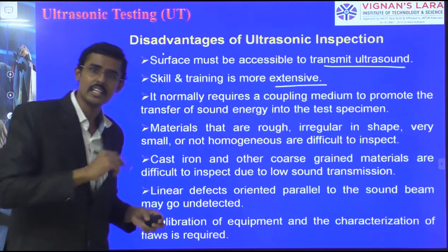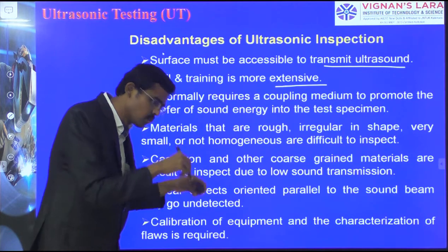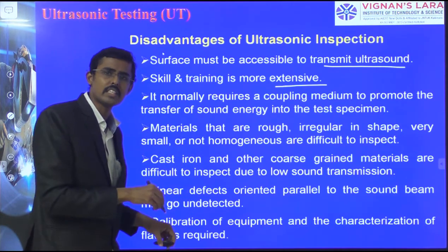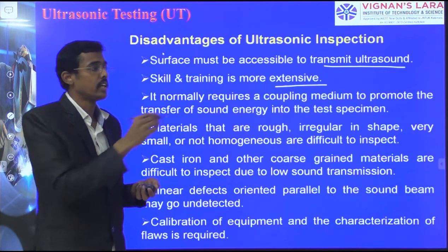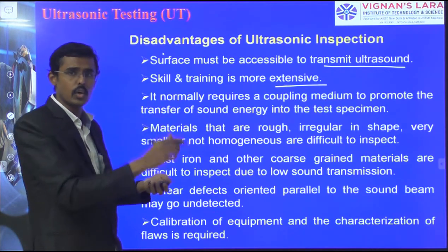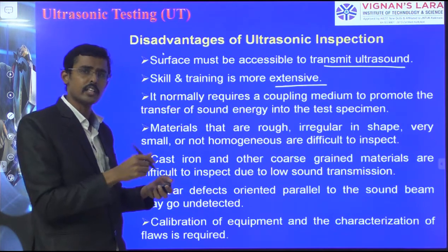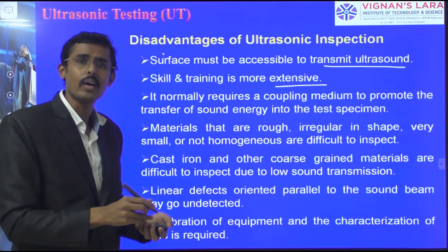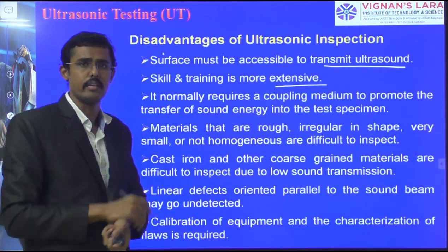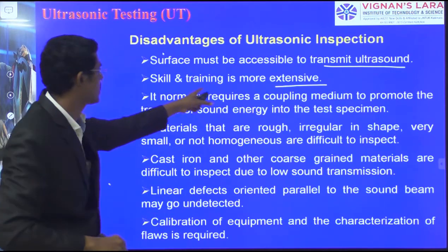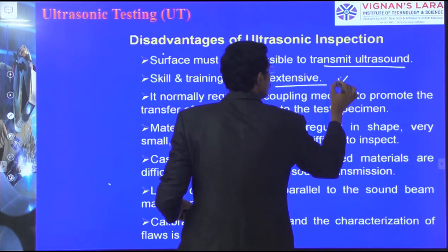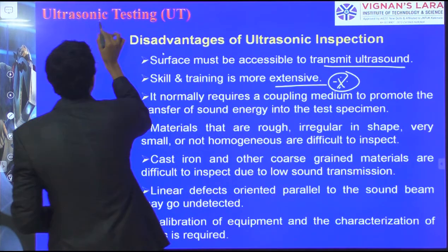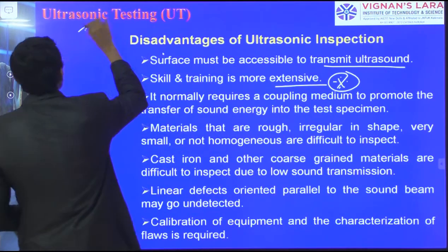It gives immediate results. If the operator is not having skill, and I am checking here, if the defect is there and the echo is showing, if he is not able to relate the echo to the defect, and he moves to the next location, what happens? The defect is not identified. Therefore, skill and training is most importantly required for this ultrasonic testing process.